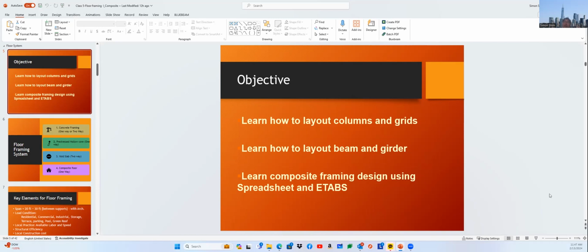We're going to talk about the column layout, and first, setting up our grid line. In ETABS, you practiced this a little bit, and I explain how to set up the grid better. If your building is pretty regular, rectangular or square, then it's much easier to set up the grid line so that you can create your 3D structural geometry by using the grid system. After the grid system is established, we usually start placing the vertical elements, columns and walls, right? You practiced it in the ETABS 101 section. We set up the grid line and draw the column.